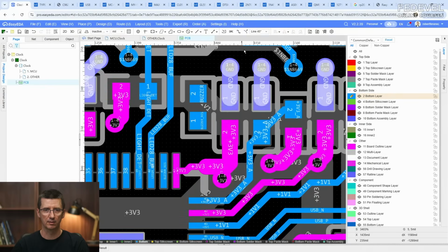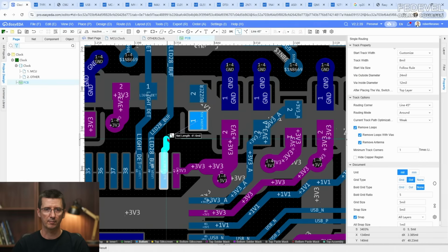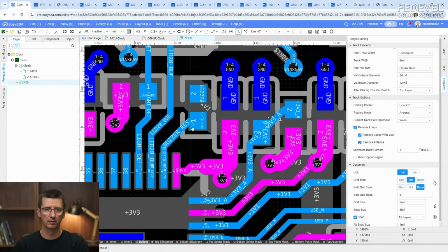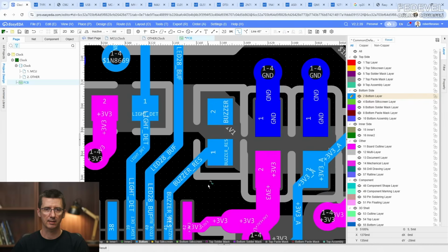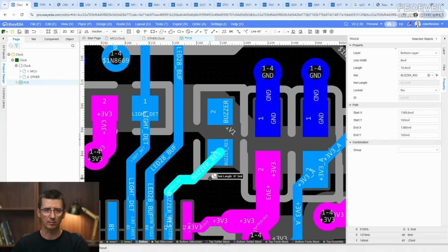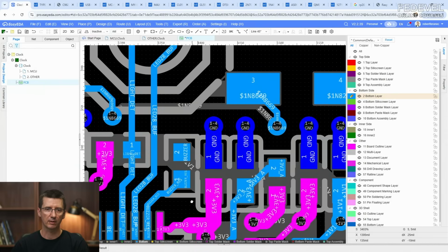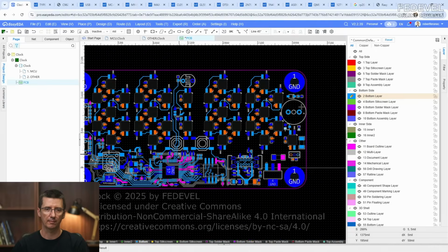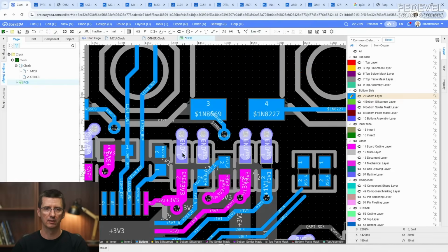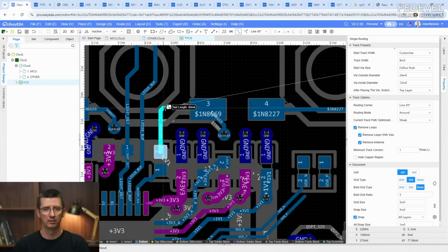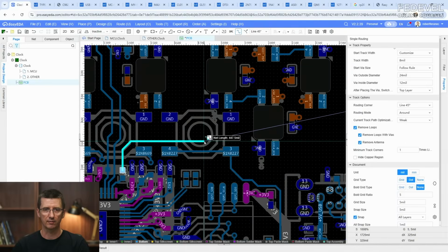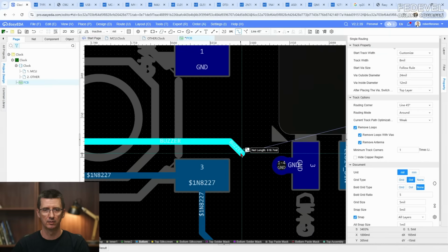What is next? This buzzer. So we are going to connect the resistor for the buzzer. I'm going to move this a little bit because sometimes PC manufacturers don't like the sharp angles, so that's why I move the track. So it just goes directly from the corner.